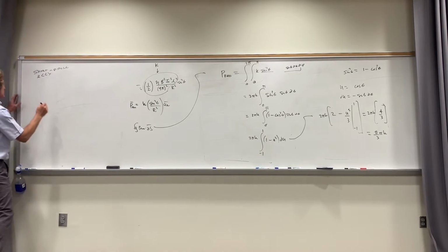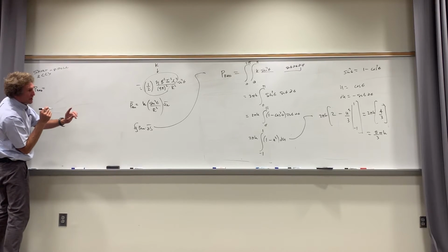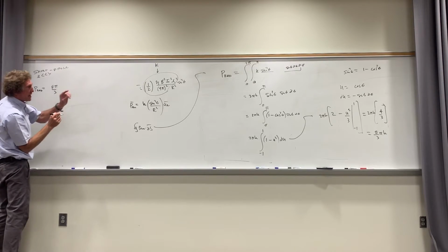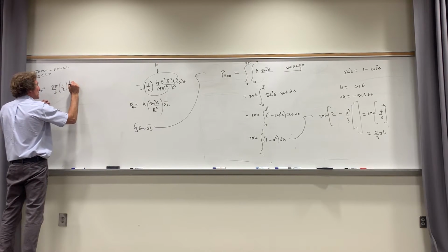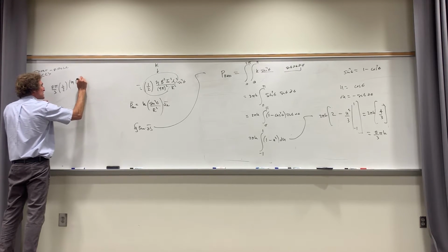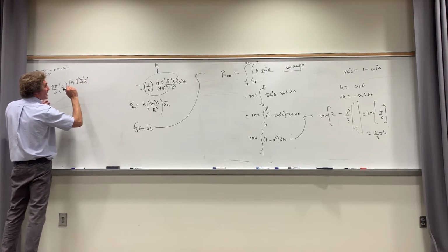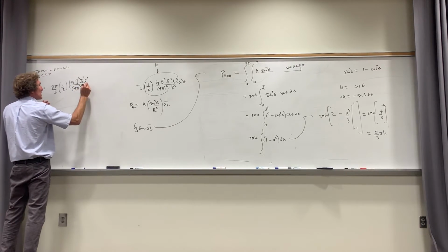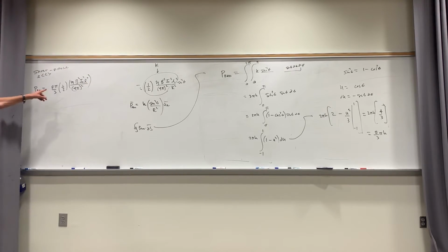So now I have total power radiated equals 8 pi over 3 times k, and k was 1/2 times eta times beta squared times I naught squared times L squared divided by 4 pi squared quantity squared, because that's what k was, so I just put in power radiated.